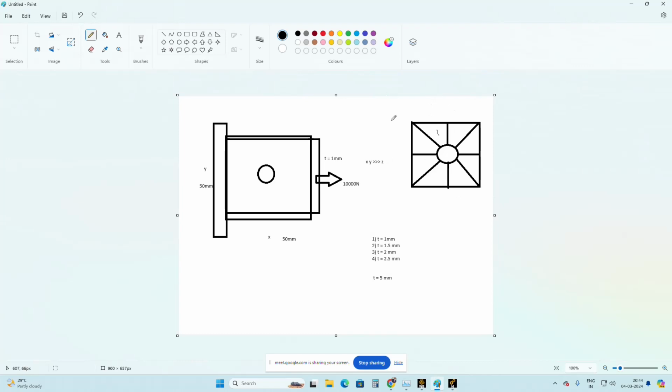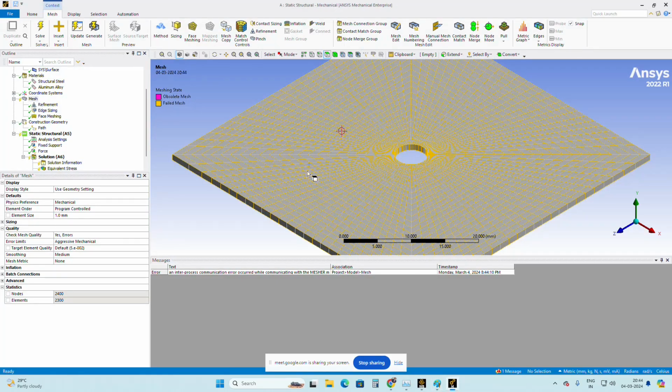Earlier, eight years back, you had to convert all the parametrical surfaces into biparametrical ones so that you could get a clear mesh. Still, if you convert the parametrical surface into biparametrical, you can get very good quality. Most people don't do much of this because of convenience. We can give the face meshing and you get it, but the problem is that if you see the statistics, the number of elements is maximum, so the computational cost will be more.